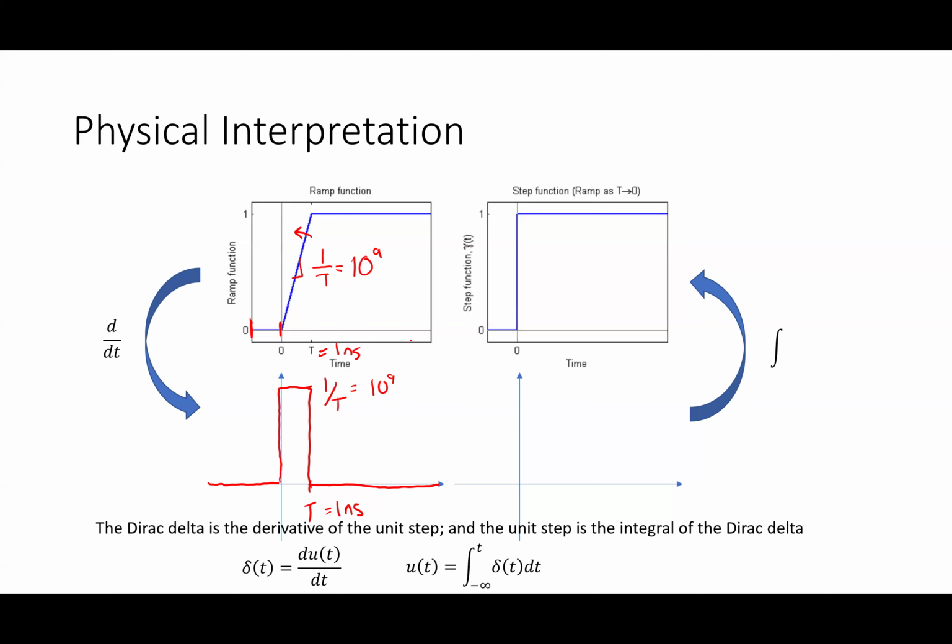this would be 10 to the 9th. Okay? So if we're talking like, I had an inductor and the current was changing, that implies that I get 10 to the 9th volts or something like that exists for some short period of time. And that happens, okay? In real world situations. I get spikes that are that big. But what happens is I try to shrink this down, right? As I make this smaller, what's going to happen to the height of this thing? It's going to go up. And in theory, if I can get t all the way to 0, if I can shrink this guy all the way down to here, what height would this reach? Yeah, it would reach infinite.